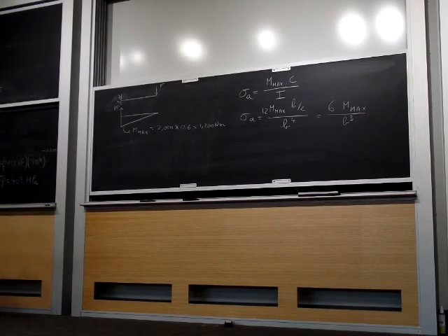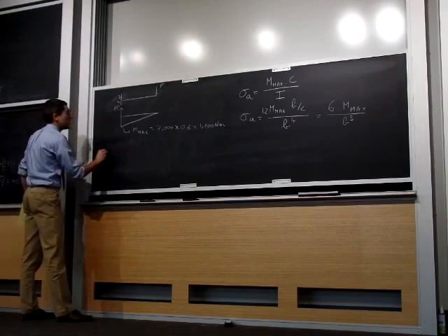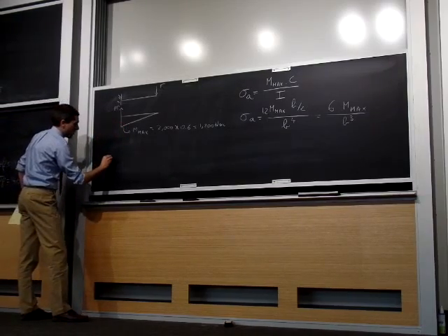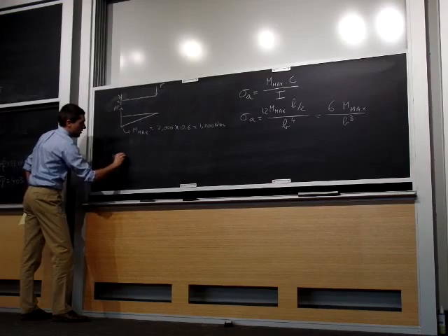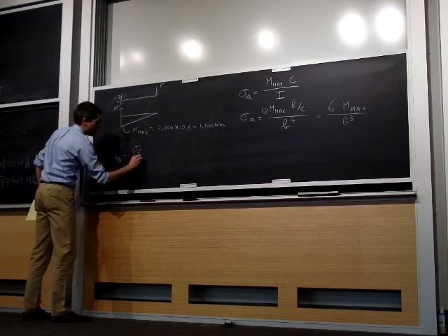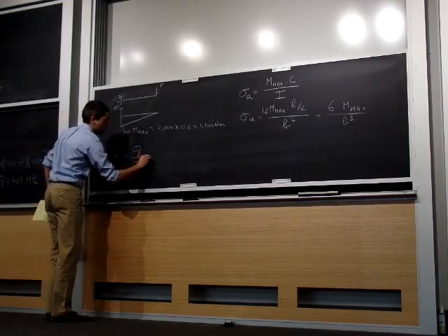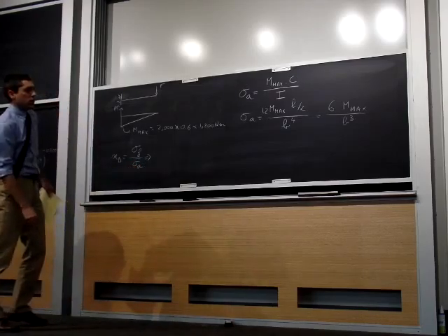And we know what M max is, so we're almost there. We can now throw everything we found into our original equation. ND is equal to sigma f over sigma a. So what did we have set as ND?